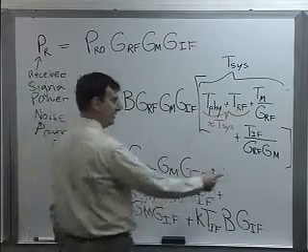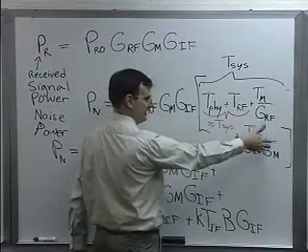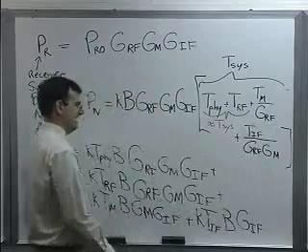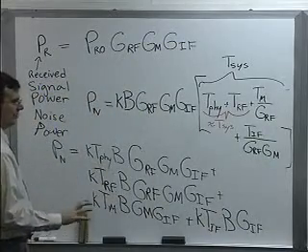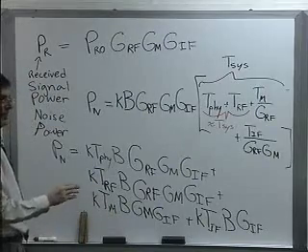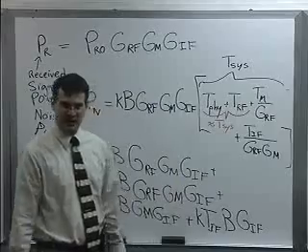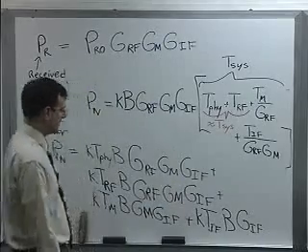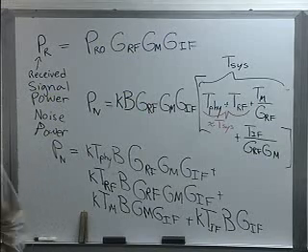But you're right in that if there's a filter in here that's lossy, then any noise that gets added in at that step or subsequently will be effectively amplified because of the loss of signal power through that device. Okay.